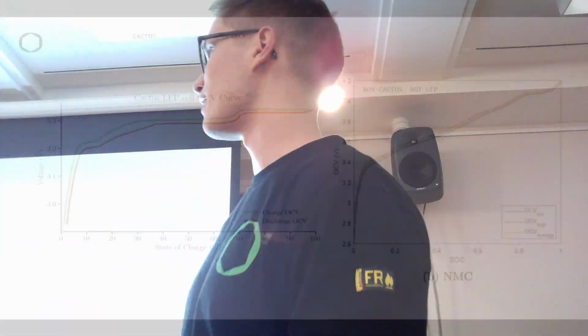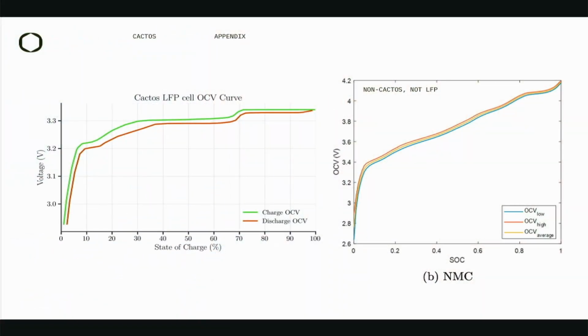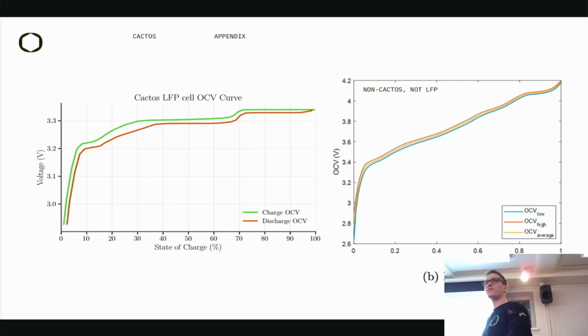Go ahead. Great talk. Wondering about this flat part, are you mitigating that by estimating the load that goes out of the battery? Yeah, that's the current integration, so Coulomb counting. So in those sections, the extended Kalman filter doesn't trust the voltage measurements, but uses the charge integration.